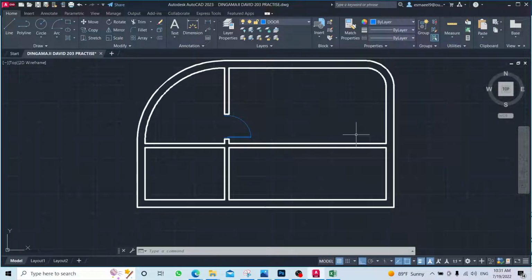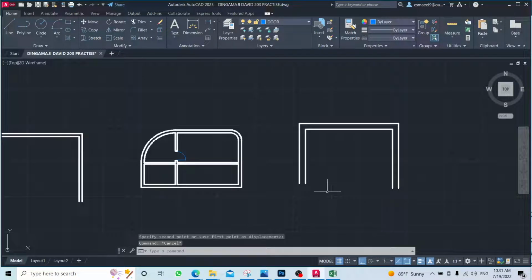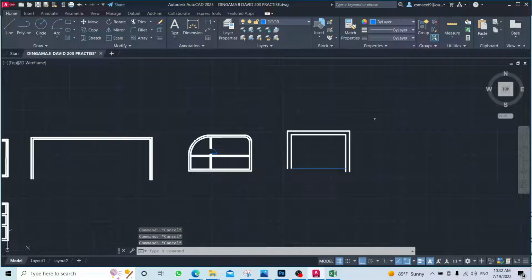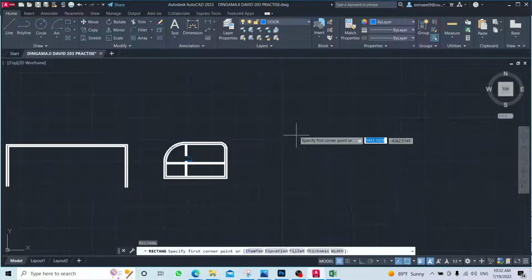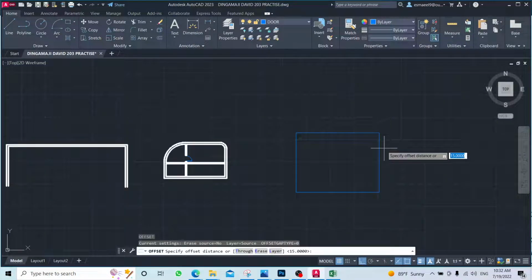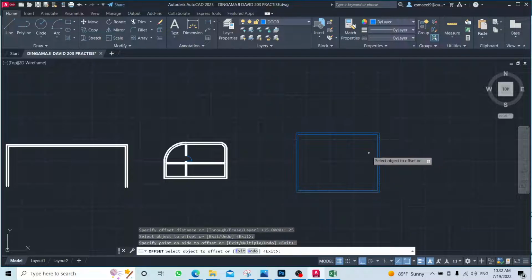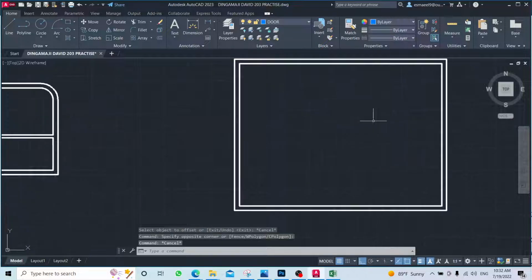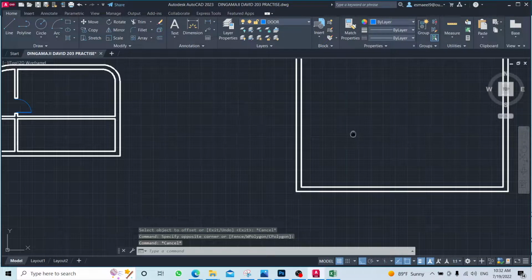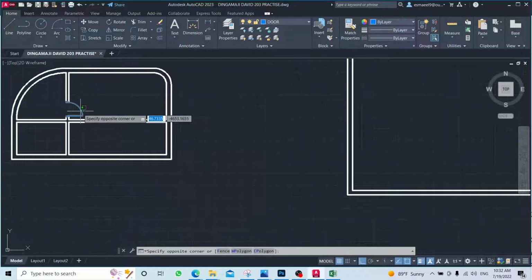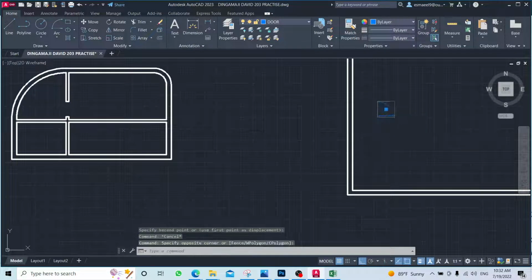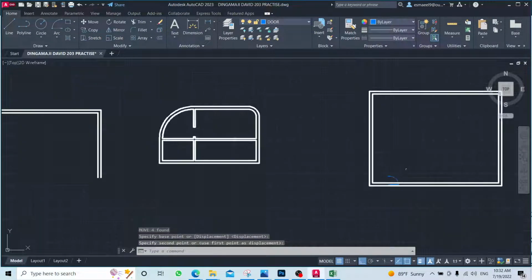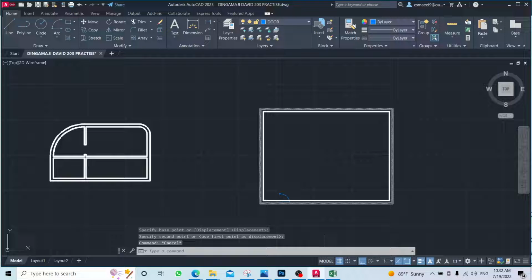Please now start working without sharing. Create exactly a rectangle like this, a rectangle room like that, and then make an offset of it 25 as walls, and select all of them. Of course, make sure that it's wall, and make sure you do have a thickness for it, and put a door somewhere. For example, put a door something like in here. Okay, put a door on this side. Please start working. I will come in a minute.